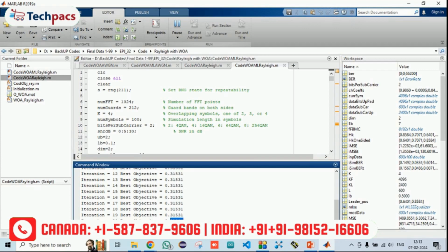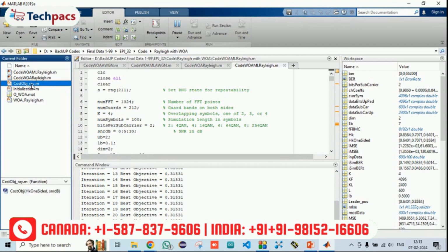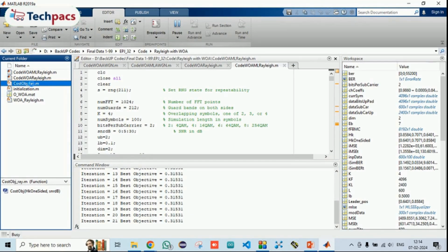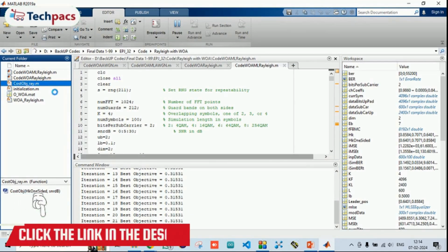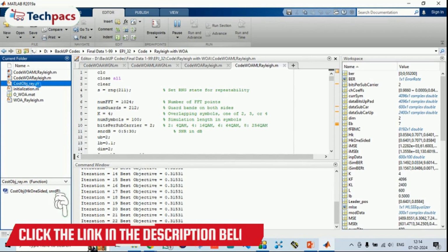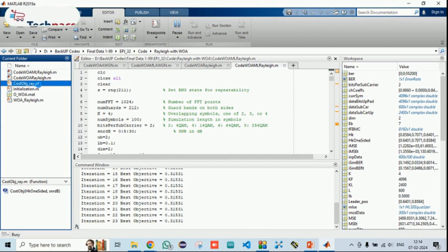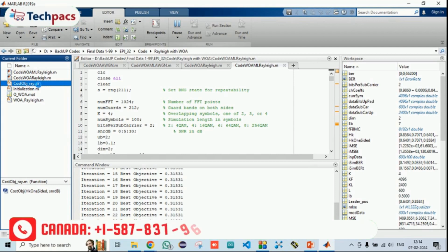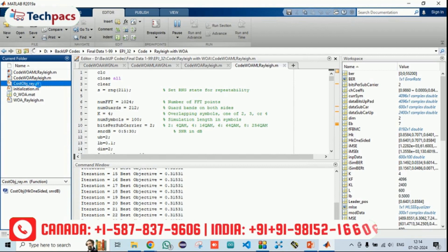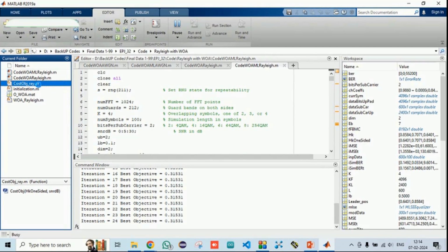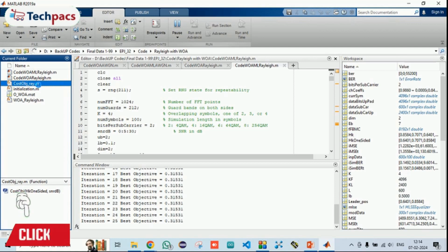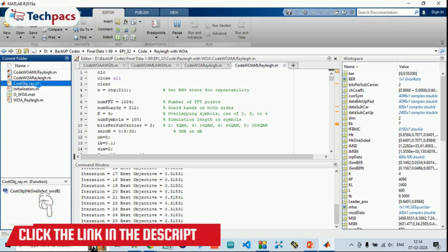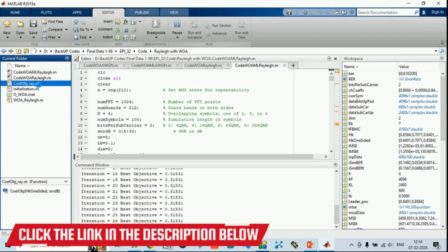The objective function that we are using is this function here. I'll also show you what we have done in the objective function once this simulation is complete. In the objective function, we are checking, when we apply the filtration on the signal, what exactly the MSE is that we receive after applying the filter with respect to the transmitted data. The coefficients with the least MSE are chosen as the best hyperparameters for the filters applied to the system, in order to reduce the error between the sent data and the received data, which is the main objective of any wireless or normal communication system.